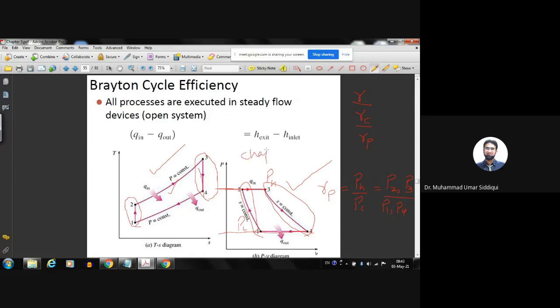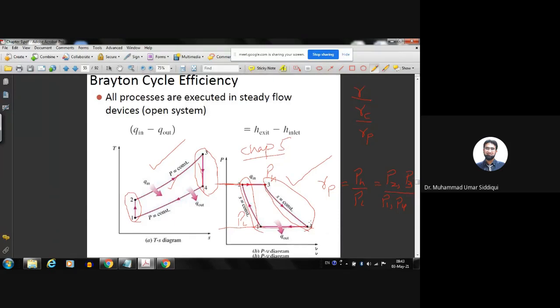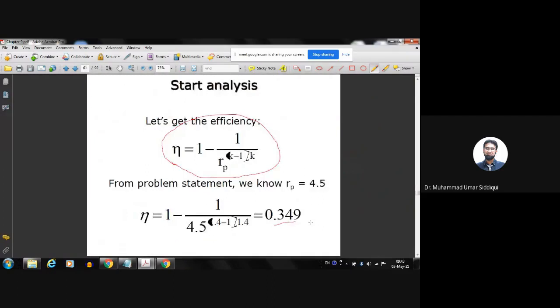In chapter number 5, we studied the turbine and the compressor, so we can determine the work output. For the isentropic case, it is obviously adiabatic, so Q will be 0. We don't have any changes in the kinetic and potential energies, so the only thing left is the change in enthalpies. Work in for the compressor will be m dot (h2 minus h1). Work out for the turbine will be m dot (h3 minus h4), and their difference is going to give us the net work output.